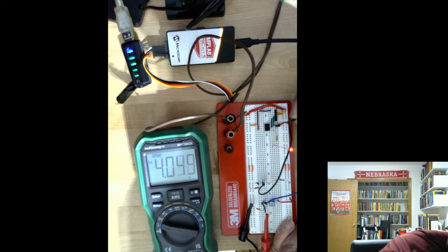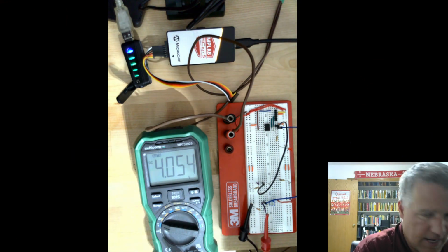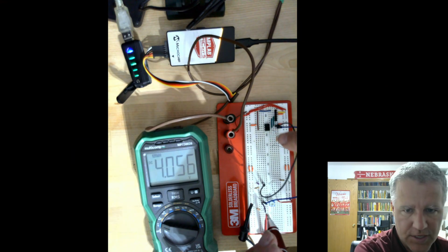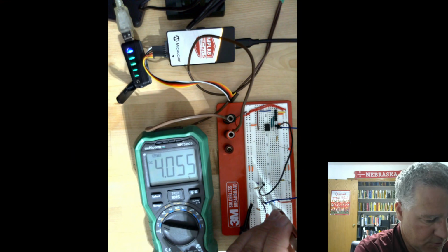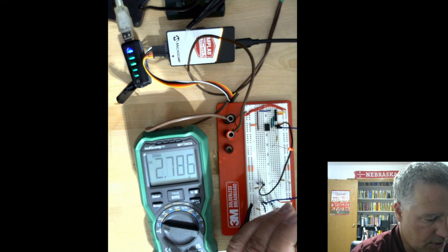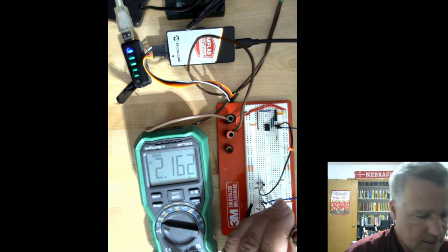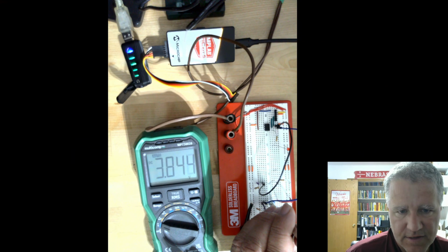Right here. Okay, so now you can see the voltage. It's being compared to 2.5 coming from this black wire and this voltage divider. Then I'm going to adjust this downward, and when we get below 2.5, I think you can see, the light comes on. So off, on.